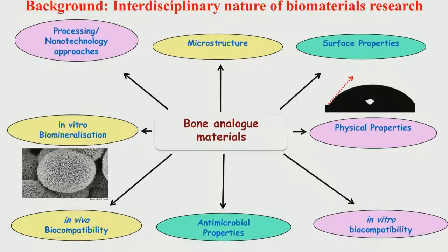And what is hydroxyapatite? Hydroxyapatite is a ceramic phase, an inorganic phase with a particular stoichiometric composition, Ca10(PO4)6(OH)2. In natural bone, hydroxyapatite nanoplatelets are dispersed in the collagenous matrix. This kind of unique structure is very difficult to mimic with any synthetic materials, but people have made significant attempts to mimic it with artificial material as close as possible to natural bone.